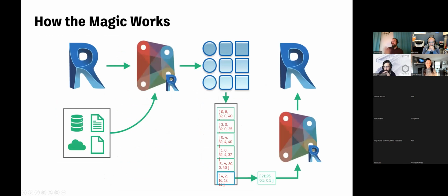So once we get those results back, we can then individually choose from those results the top performing one, which was the best option, select that option, and then have generative design send it to a copy of Dynamo for Revit instead of Dynamo Sandbox, or Dynamo for Civil, or whatever version of Dynamo we might want to work in, and back out and record that data by making elements in Revit, objects in Civil 3D, or saving an Excel file or generating an IFC, whatever sort of decision process you might want to make. So where do we want to?